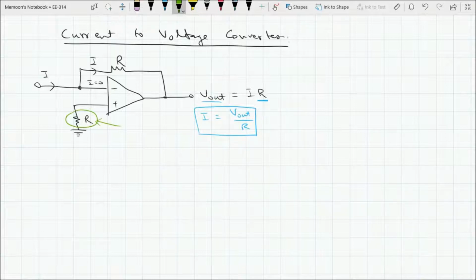If you remember that in electronics 1, you used to add an emitter resistor, and that provided temperature stability to the amplifier circuit. That was also a transistor acting as an amplifier. So the proof of how this R gives temperature stability is provided in your electronics 1, and you have already studied that. Just here I am using that concept again.